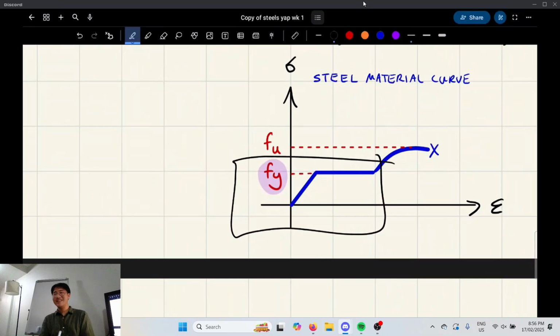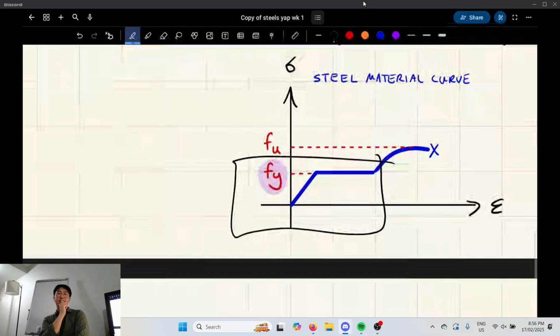Wait, why can't you just keep it there even if it's a little bit stretched? I think it's because once it's already stretched, once it's yielded, you'll never go back to its original strength. Yeah, it's plastic. If you put on a load that caused it to yield, then it will yield way more than it first did, because it's not as strong as it was originally.